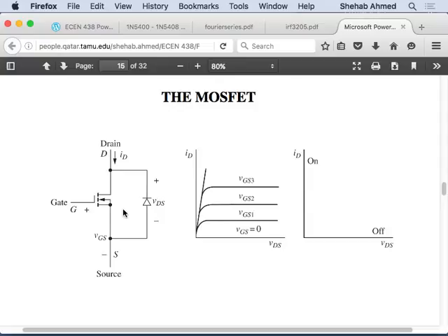So this device is beneficial for me if I'm able to block positive voltage, or if I give it a gate signal, I can conduct positive current. Can I conduct negative current? No. Negative current will also be current that's flowing through the diode, so it's useless. It's uncontrolled. So this device is good for controlling positive current flow and for blocking positive voltage.